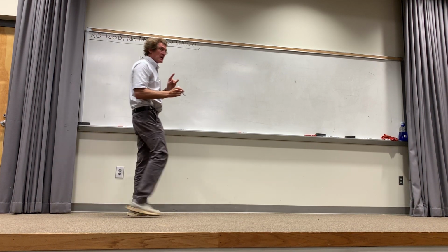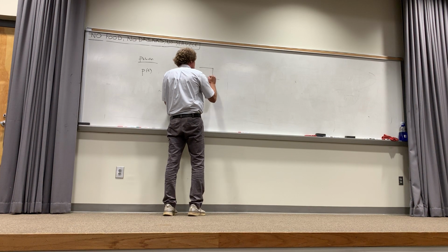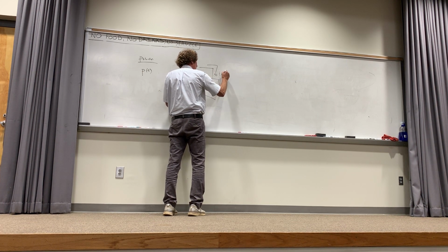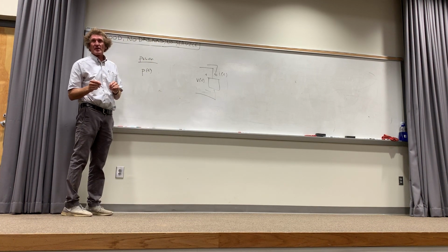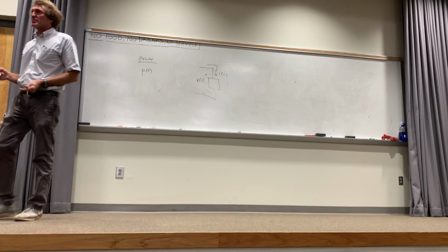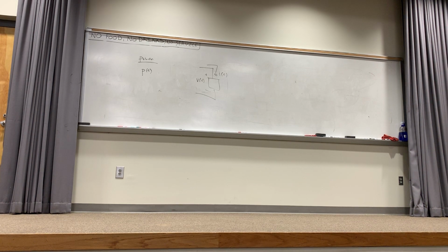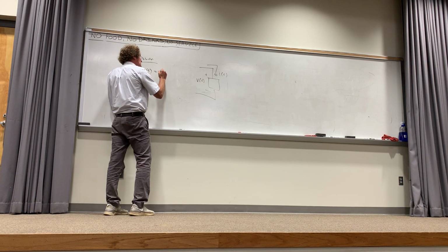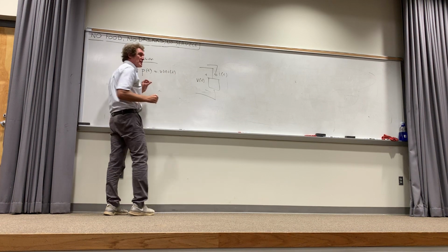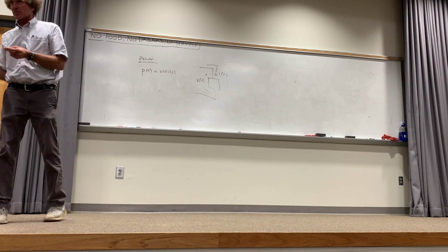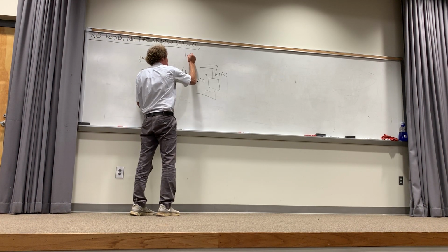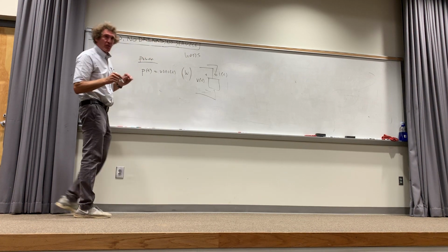And in general, if you have any element here, doesn't matter what it is, and this is going to be in the time domain, all right? And you have a voltage across this element, some v of t, and current i of t entering the positive terminal of that element. It could be a resistor, a resistor capacitor, a resistor capacitor inductor. It doesn't matter what's in that box. But if you have the current and the voltage, then the instantaneous power is equal to v of t times i of t. Now v is in volts, i is in amps. Power has the units of watts. The symbol is capital W, and it's watts, named for James Watt. All right, that's power.